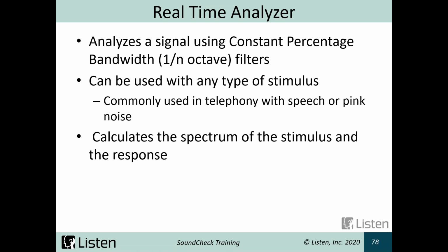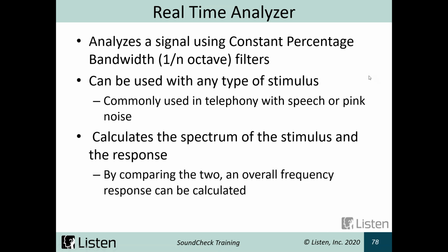One major difference is that it also calculates the spectrum of the stimulus in addition to the response. RTA can compare the two and give us an overall frequency response calculated with the spectrum of the stimulus versus the spectrum of the response.